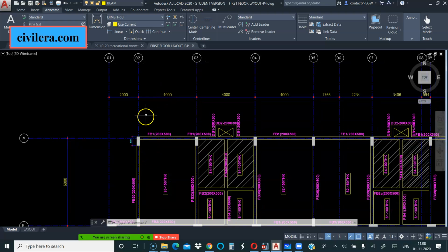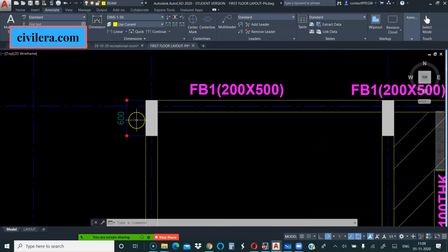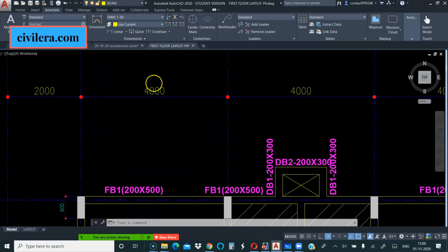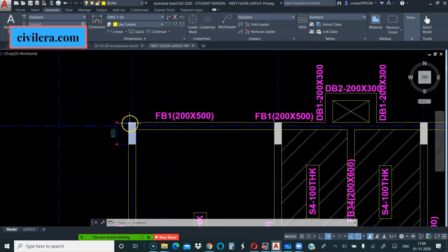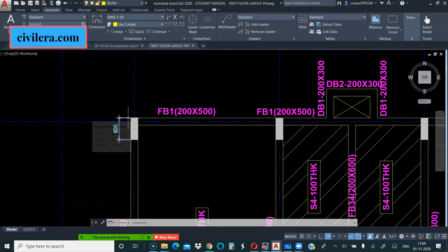So from a gravity load point of view, you can understand that your moment will be more from this frame than this frame. So I have oriented it in this direction. I hope that's clear. Now, if this span was 7 meters, I might have kept the column in the other direction in my first analysis. So that's a simple rule that you can follow. Now, this is for gravity loads, for dead load, live load.